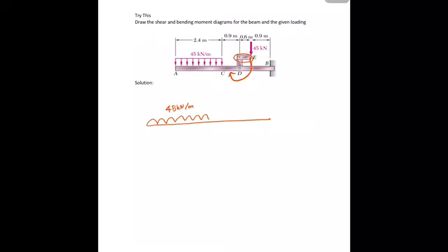And then at point D, you have two loads, which is 45, the applied load, and also the moment because of the rotation from the secondary beam. 45 times 0.6 is equal to 27. And then you have the fixed point. This is point A, point C, point D, and point B. There is no point E.